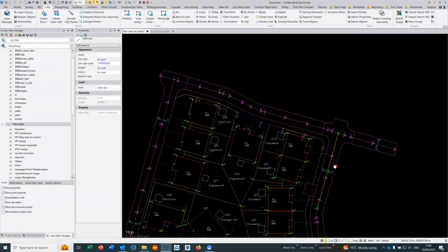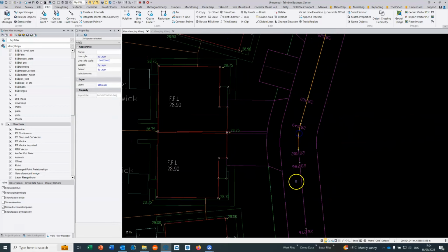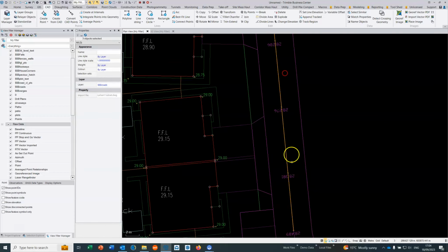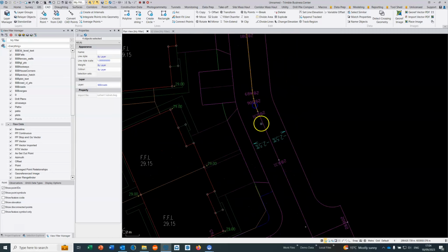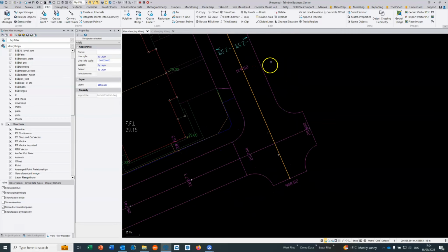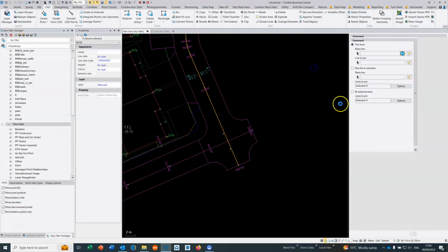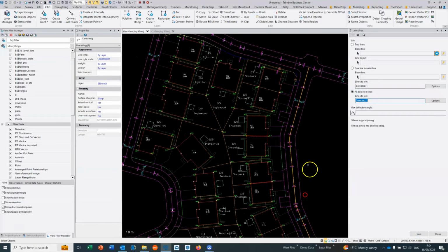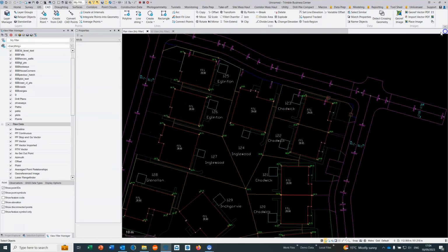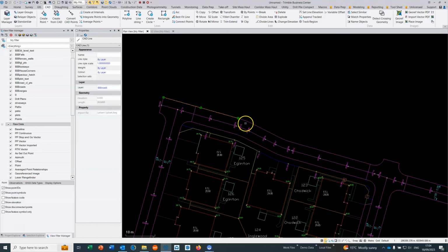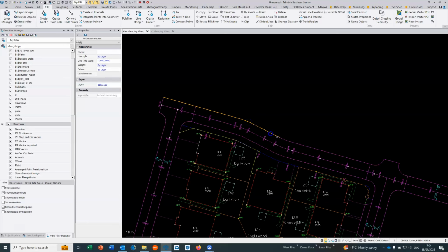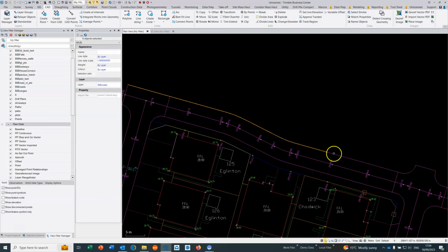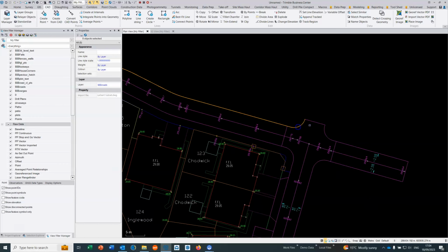And I'll just do the same for this one here, so just Control clicking all the way through, and then right-click now and join lines, because it's a recent command, all selected lines, and we can do that now. What I'll also do is I'll actually do it for the channel information, so I'm just going to select here, and if you've got a more advanced version of Trimble Business Centre, then the project cleanup can do all this sort of stuff automatically.